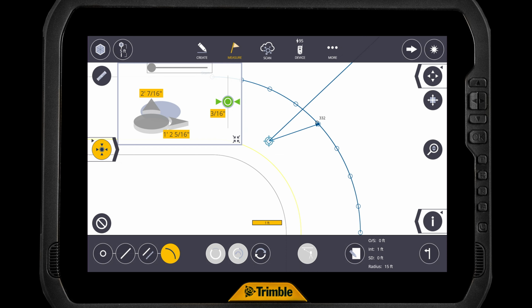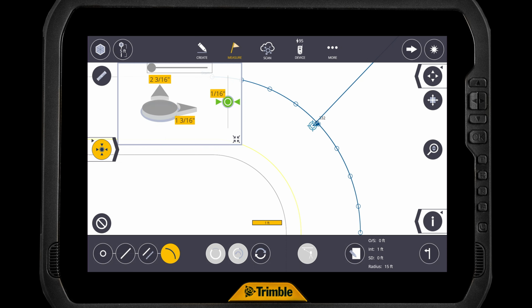You'll see as I move close here, it gives me the right to left, the forward. Once I get within my tolerance, it's going to give me the lovely green stake. And when I stake that, even though I didn't create a point initially in my drawing, once I stake it, it will save that as a staked point. And it is the same type of point that you would have from any other kind of stakeout. And then you can put a layout report, all that kind of fun stuff.